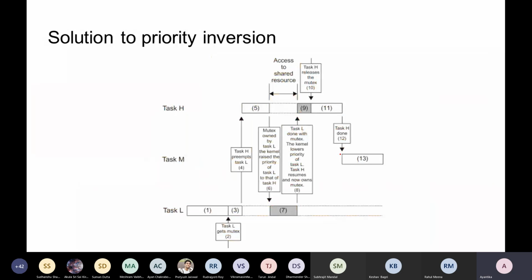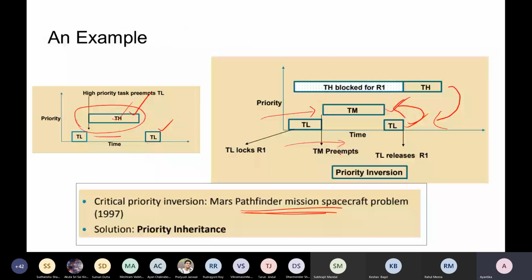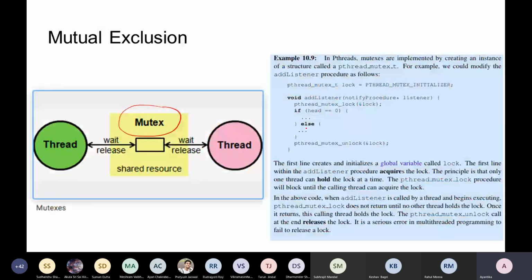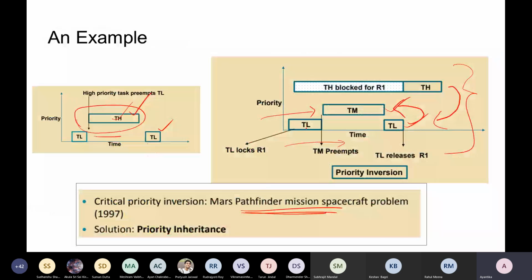So after that, with this experience, researchers came up with a rule for future cases of sharing resources. One typical rule was that whenever any task enters this mutex handling scenario, where we are working with some shared resource, it will automatically take the highest priority, so that no medium priority task can preempt and delay any high priority task. That scenario is called priority inheritance.